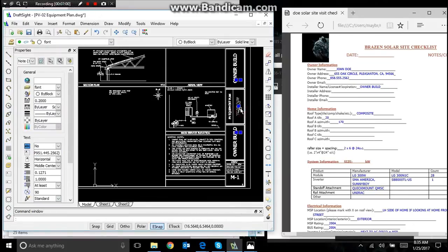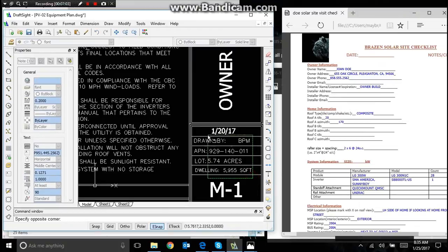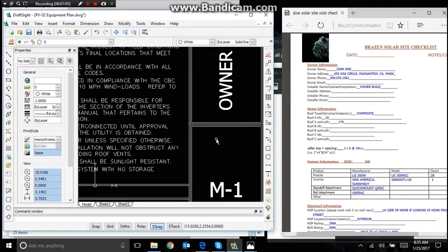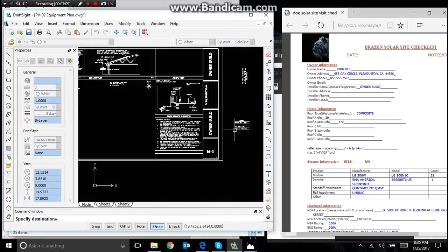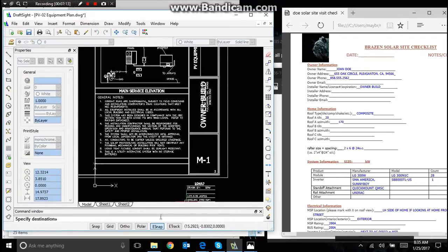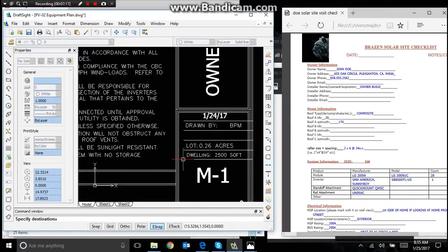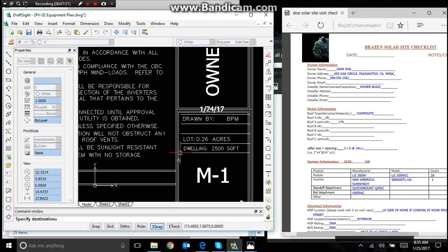Now, for this, it's very easy. I can just delete what is there, and I can Control V, paste my information from the first page. In this case, it is helpful to have that snap-on because you see what it selects? When you paste it, you can select that midpoint right there.